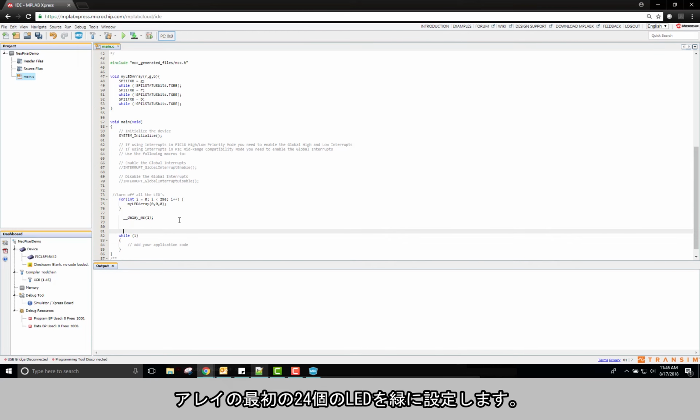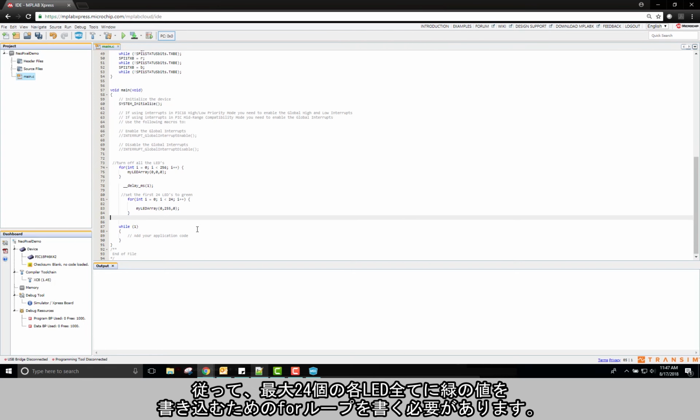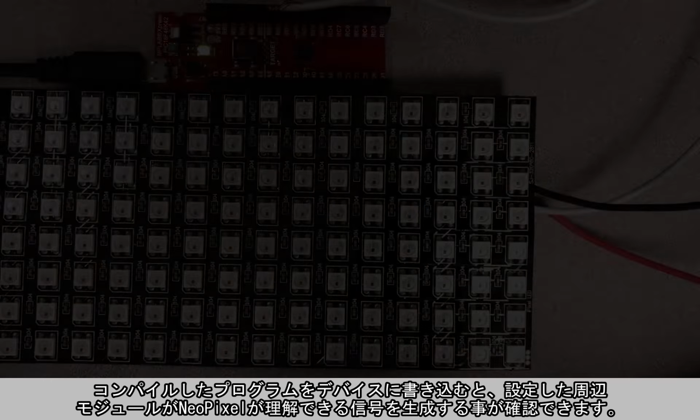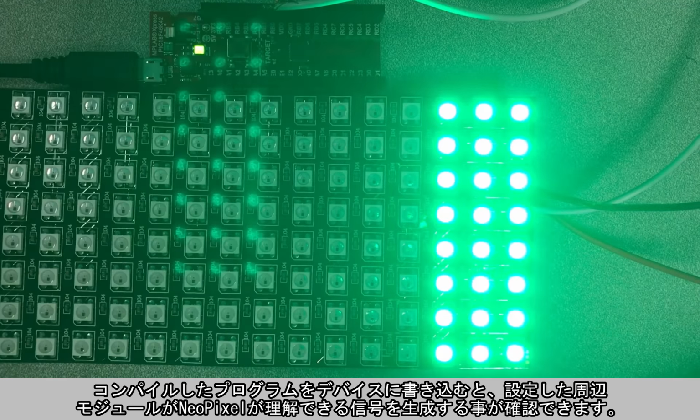I would like to set the first 24 LEDs of the array to green. Therefore, I will need to write a for loop to write a green value to every single LED up to 24. After I make and program the device, you can see that our custom peripheral serves its purpose in generating a signal that our Neopixels can understand.